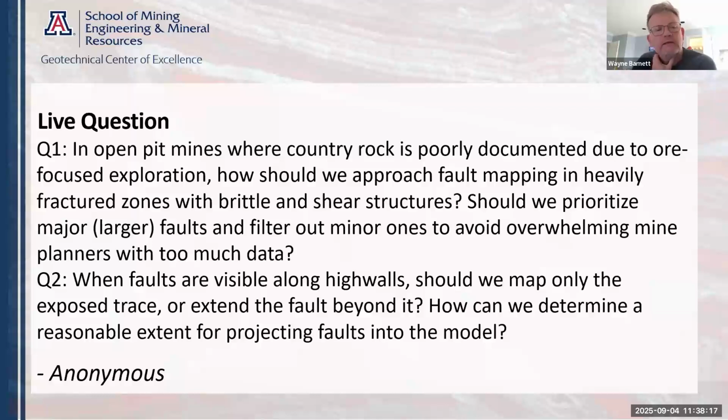Yeah, I support that. I like to try and map everything, but you can never do that, right? Well, I think with these drone scan imagery, we can probably do a lot more detailed work. In terms of overwhelming, you do obviously have to focus on what you think the highest risks are, and if you've got large structures that are potentially a risk of causing slope instability, then you've got to focus on making sure that you really understand those larger structures best, and what their properties are.